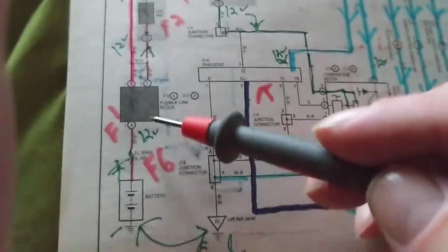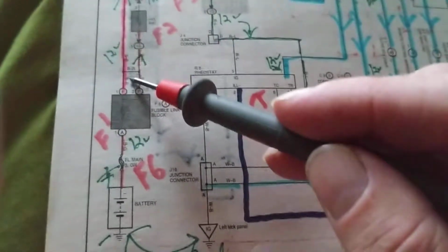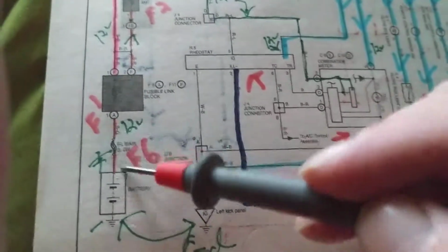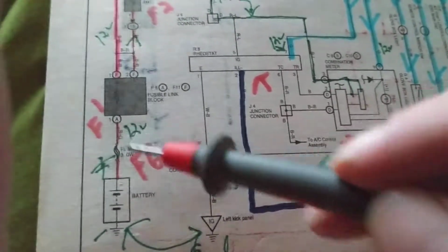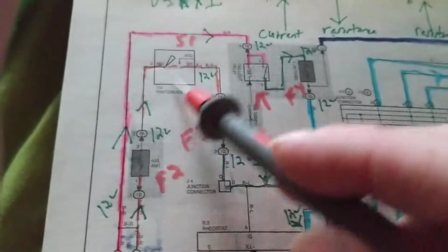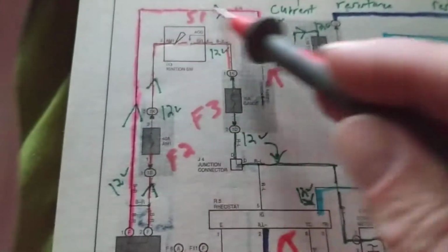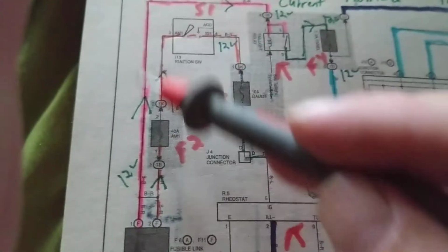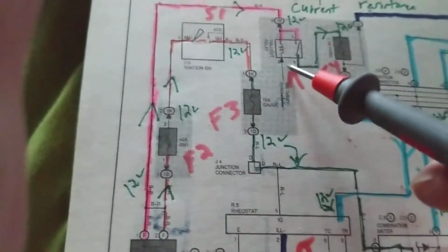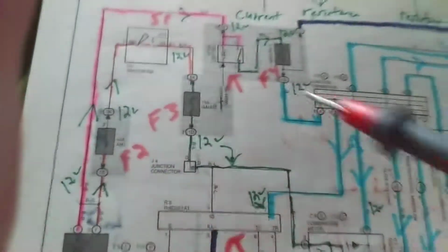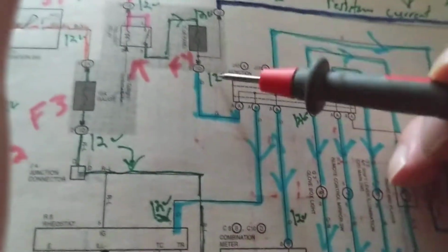Well, let's go and measure. 0 volts here, 0 volts here, 12 volts here. Aha, this is open. I have 12 volts here. I have 0 volts here. If I measure 12 volts here, 12 volts here, and I come over here, 0 volts. Where did I lose it? Between this connection right here. Maybe the connector is broken. Maybe it's open. Okay? That's how you go about it. Again, 12 volts here, 12 volts here. That's good. That means I have it.